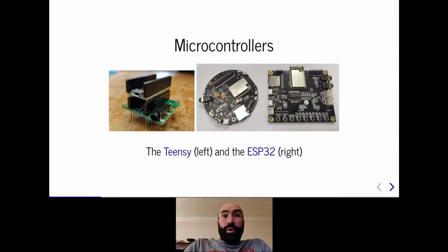Some microcontroller-based boards, such as the LilyGO TTGO T-Audio, provide a comprehensive solution for real-time audio processing applications by hosting an audio codec and an external RAM module. Other brands and boards, like the Teensy, distribute an audio shield, which is essentially a breakout board for an audio codec with the correct form factor to be mounted on the main board. Programming microcontrollers for real-time audio signal processing applications is a more complex task than on embedded Linux systems because the use of C++ is always required at the end of the toolchain.